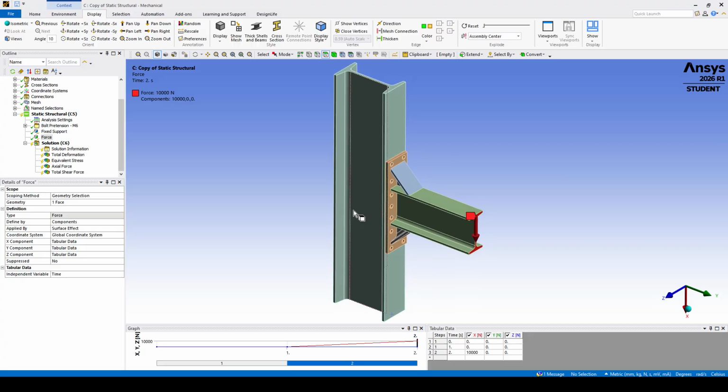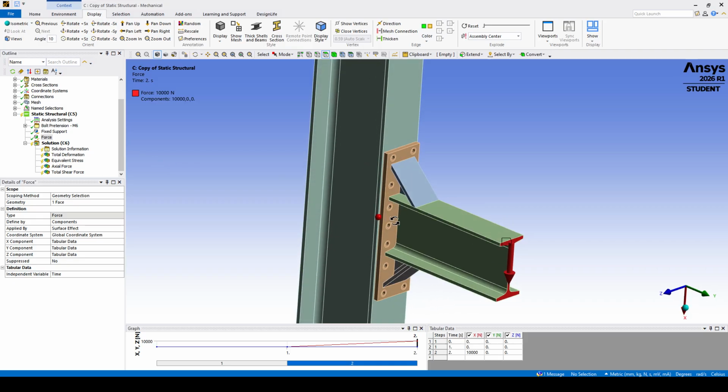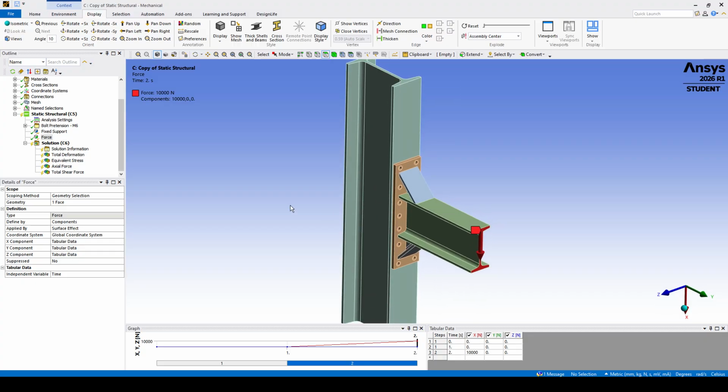According to VDE 2230, which is a standard mostly used, and famous, in Europe to check bolts to see if they are okay or not. So in my case, after defining the fixed support and the force that I have, I still have to define a bolt pretension for every edge.